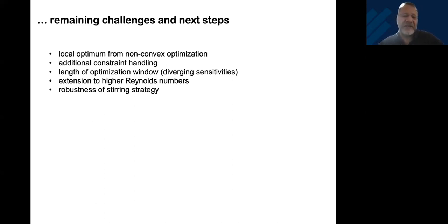This is a phenomenon you often have with chaotic systems or turbulent systems. And that's why we wanted to stay away from turbulence, because the adjoint would somehow not bring back any usable gradient information. We want to go to a higher Reynolds number. The simulations that Max is running right now are at a Reynolds number of 10,000 and a Peclet number of 100. So we're getting closer to the liquid regime.